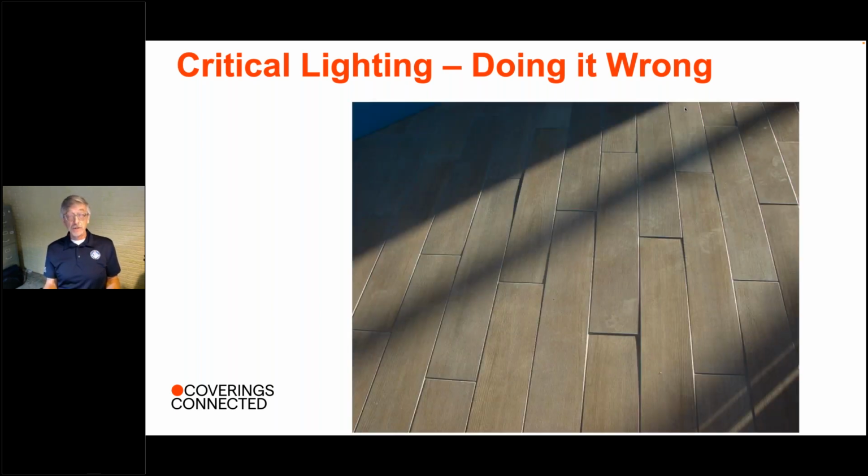This is the first time I'm showing you a floor like this one with a large format tile, a plank tile, and it doesn't look wonderful, does it? I can think of a few possible causes of where things went wrong here. Maybe that substrate wasn't flat enough or to meet industry standards. Maybe that tile had some warpage beyond the manufacturing standards.